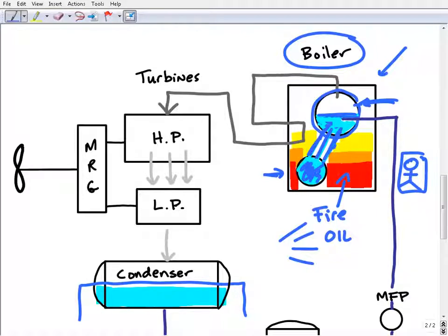All right, so this is where we're going to continue this process forward. Now that we've got steam, this is very, very powerful steam at this stage of the game. It's what we call saturated steam, or wet steam. Depending on your boiler type, you could be coming out of the boiler at, let's say, maybe 700 psi.